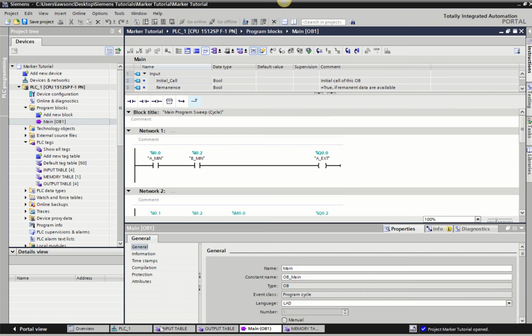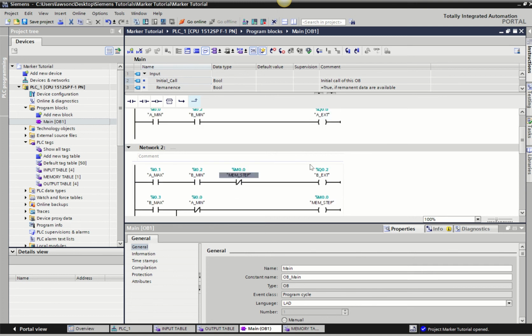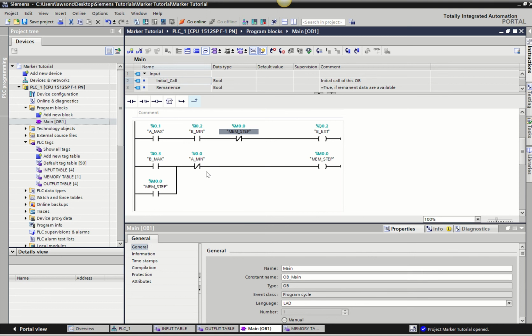Now the code may not be completely bulletproof because, depending on the outputs and the inputs you have, you may get a different solution. If the output needs to be latched on to allow the cylinder to fully extend, that will change your coding ever so slightly. In the same way, it depends on how you wire up your inputs; we're assuming these are all wired in as normally open. But you get the idea, and hopefully it shows you an area where memory plays an important role.